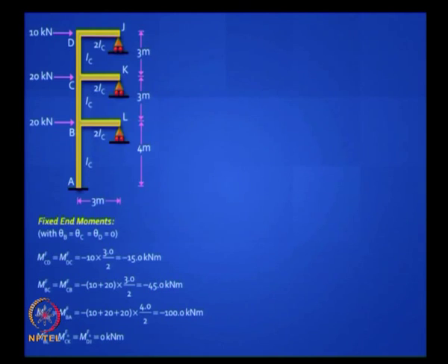So when you arrest theta B, theta C, theta D and you apply the lateral loads, you will have 3 independent movements. Each of those columns in each of those stories will just move like a beam undergoing settlement of supports, right. So everything is known.